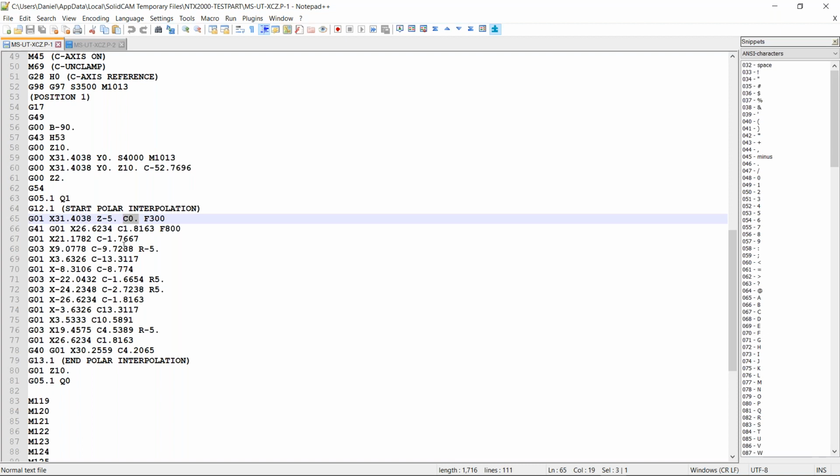how you can actually test this? This is the right question. Okay, because now you are getting some strange values, and how you can actually test this on the machine. There are 2 ways, and I will just give you small advices. The first, try with some very simple geometry. Even though this is very simple geometry, you can also test it, but try with something very simple, like a square, and try to see how the machine actually rotates the Z-axis, okay, in which direction, and make sure that this is actually done correctly.